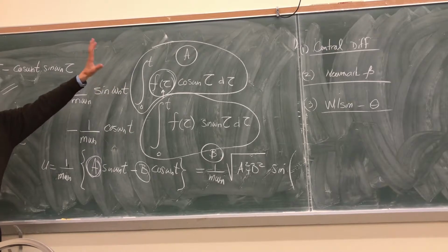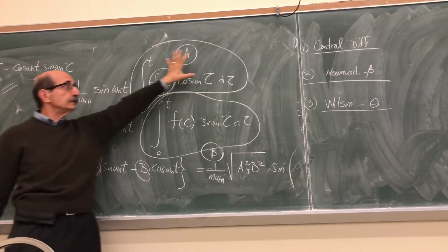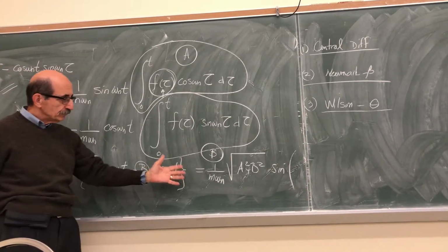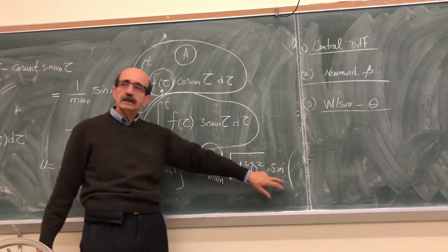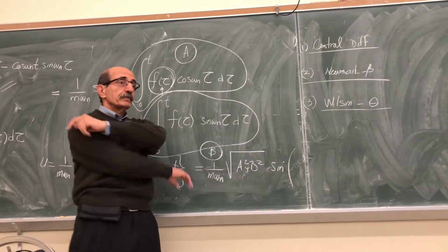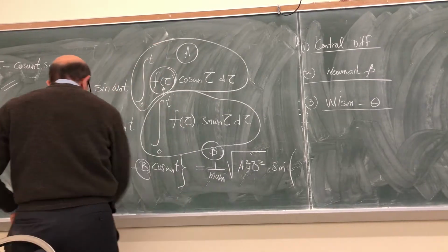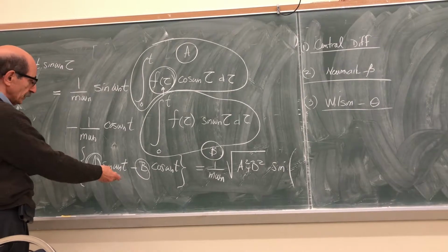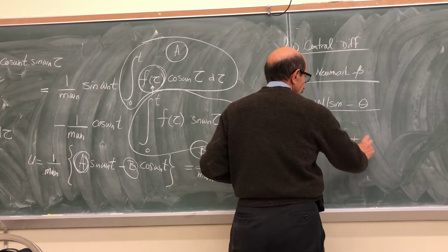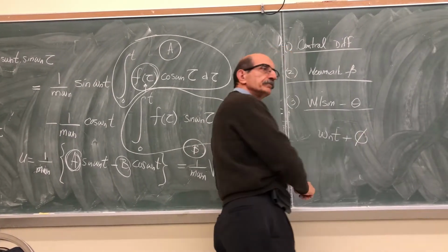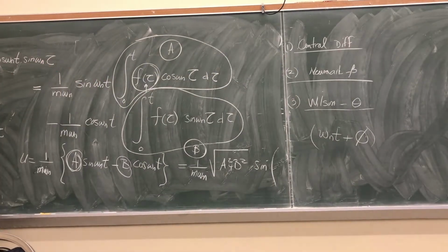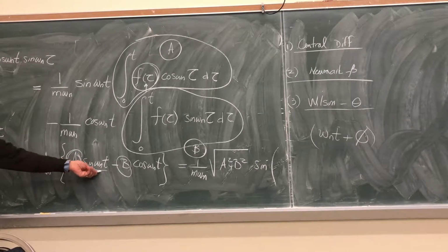We use a numerical method approach to evaluate these integrals, but at the end, the Duhamel integral is reduced down to nothing more than a harmonic function, except the amplitude is time dependent. Yes? What would be inside the sine function? It's like the usual things: you will have omega n t plus some phase angle, because omega n still is the frequency of this.